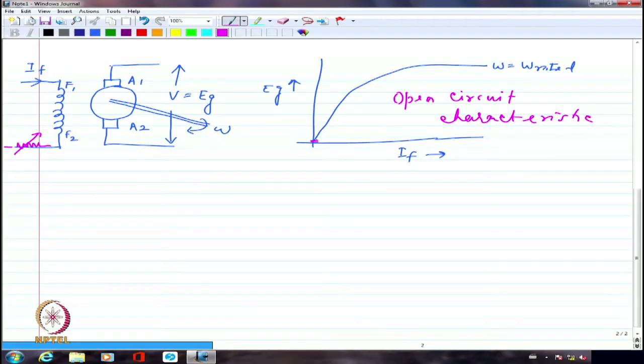If there is residual flux, normally there will be residual flux. Unless I repeatedly excite the field in two opposite directions, which I won't do in a DC machine normally. I will try to excite it only in one particular direction. If I am trying to excite it once in the positive direction, once in the opposite direction, and keep doing that repeatedly, I'm not going to have any residual flux left over. Not much, really. So I would basically try to do only one direction excitation.